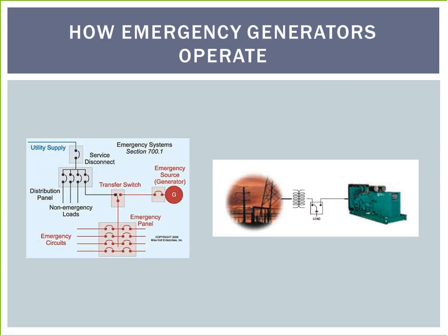Main power can be lost due to down power lines, malfunctions at substations, inclement weather, planned blackouts, or in extreme cases, a grid-wide failure. In modern buildings, most emergency power systems have been and are still based on generators. Usually, these generators are diesel engine driven, although smaller buildings may use a gasoline engine driven generator and larger ones a gas turbine. However, lately, more use is being made of deep cycle batteries and other technologies such as flywheel energy storage or fuel cells.